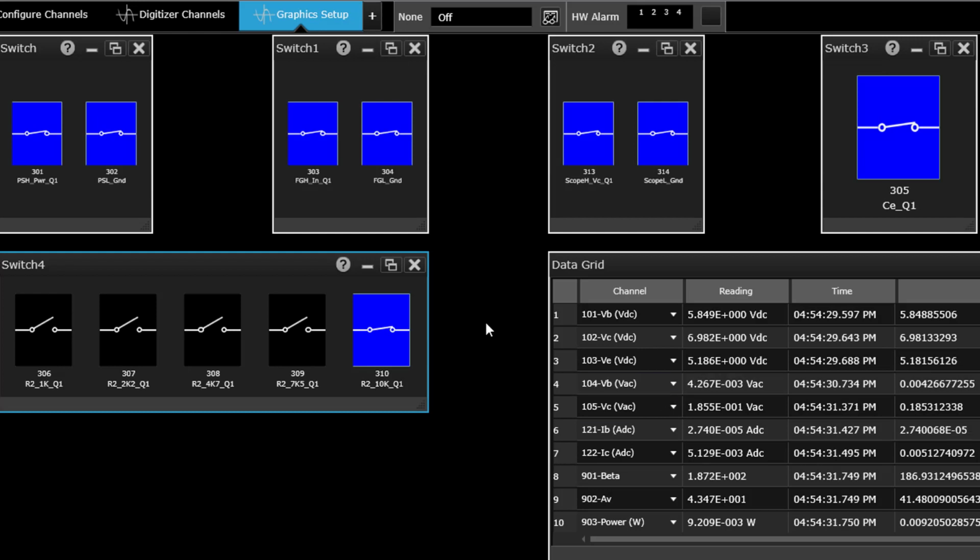Now there's a 12-volt supply going into the circuit, and a 1K load resistor and a 1K emitter resistor. So the DC bias point, it will be the base voltage, 5.8 in this case, using the R2 of 10K over here. If we subtract 6 or 7 tenths of a volt for the base emitter diode junction, then we'd expect the emitter voltage to be about 7 tenths less than that, and it is 5.1. It's going to result in 5 milliamps of collector to emitter current. Well, 5 milliamps going through a 1K resistor is 5 volts, so we'd expect the collector voltage to be 12 minus 5, or about 7. If we look at the collector voltage, you can see it is about 7.